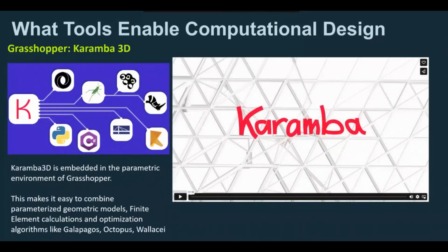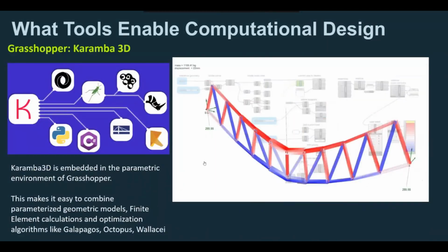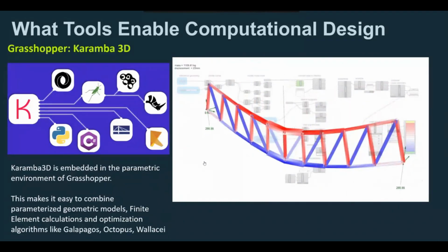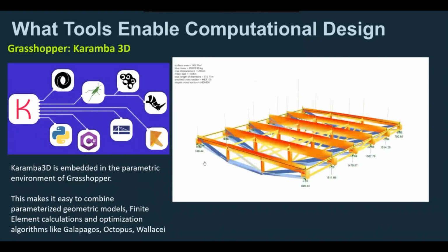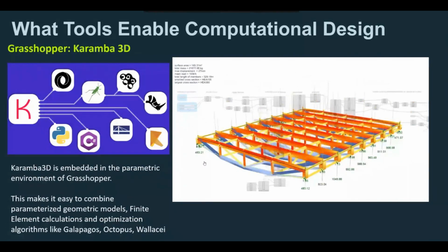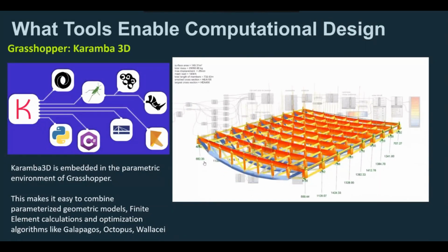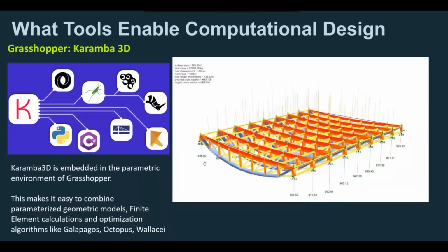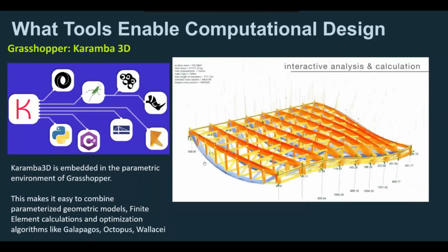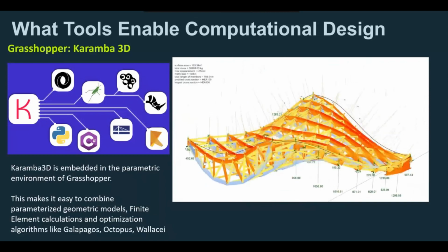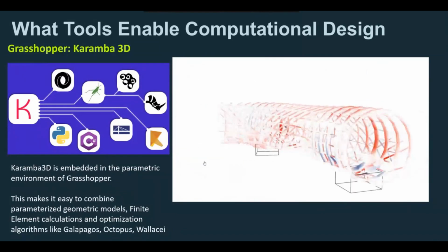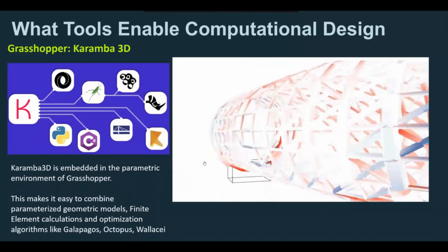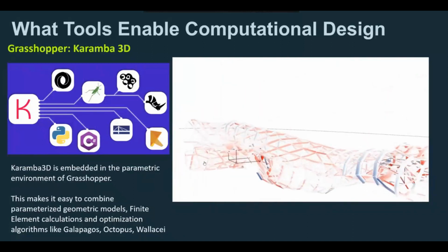So what is Karamba? A couple of solutions come into here. It has got a truss. You can simply set endpoints. You get the behavior. You can do a moving load analysis at the same time. Then you can expand your reach if it's a deck, and then you will get bending moment, shear forces, and it's all active. You don't click a run. You actively change. So as you move your model up and down, the analysis is changing. That helps me, and always helped me make a better engineering judgment there.